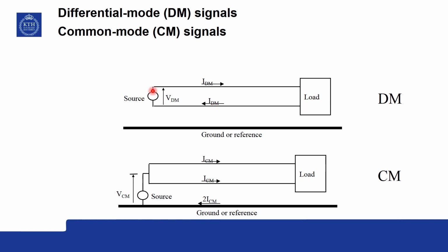So, normal signals are all differential mode signals, and there can be some noise, EMI also, circulating in the differential mode, say for example, some of the switching noise or some other electronic noise. So, this is a ground plane, but it could also happen that you have some electromagnetic fields coming from some other direction and falling on this circuit over here.